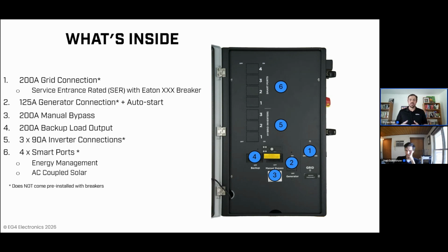That replaces what you see with a lot of systems in the market requiring external combiner panels, where you need to have a single point where the output of multiple inverters is actually combined to a single source before you take it to the rest of the home's loads to be distributed back out across your branch circuits. Again, significantly decreases installation complexity by giving a single piece of equipment that enables up to 3 inverters to be paralleled right at the device with no extra balance of system.